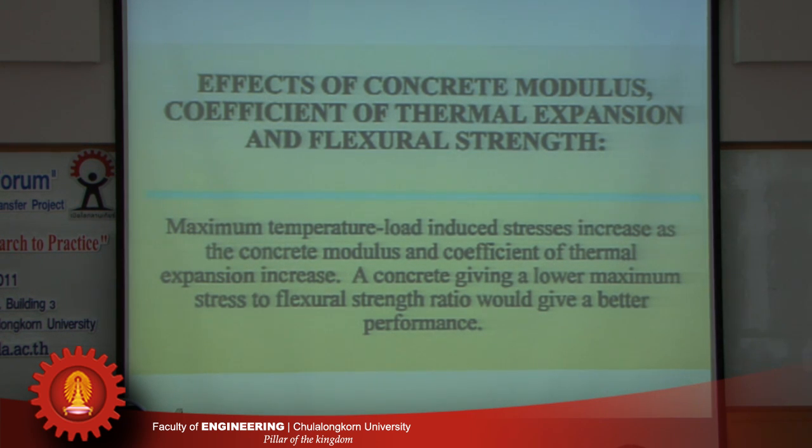So if you're comparing different concrete mixtures to see which one would perform better, we cannot just judge it based on strength alone. A concrete with a higher strength may not perform better. We have to do proper analysis.